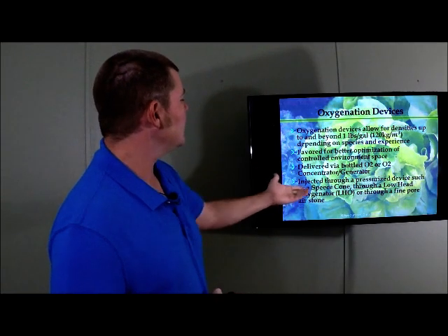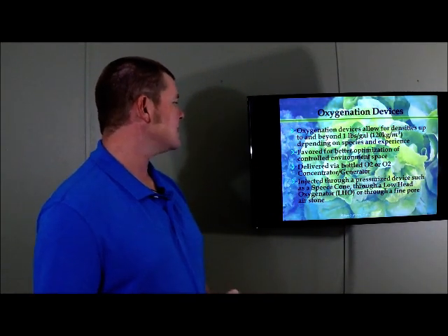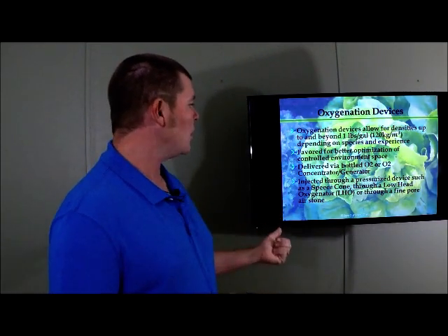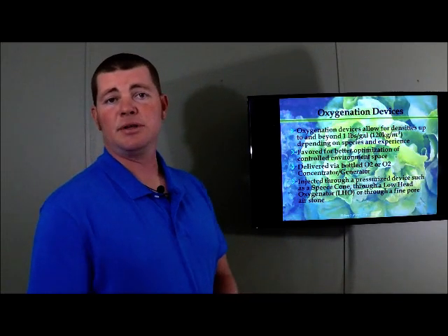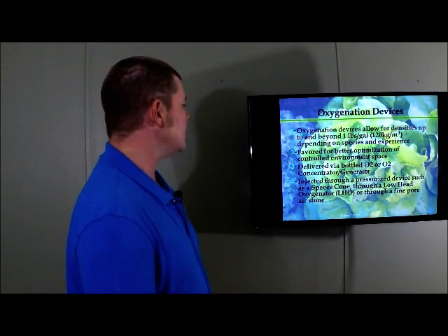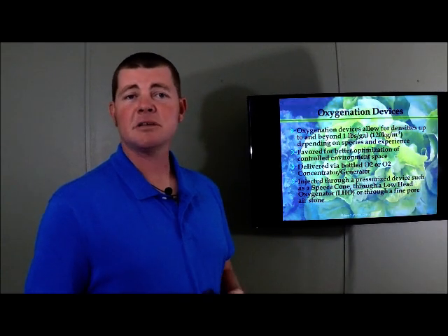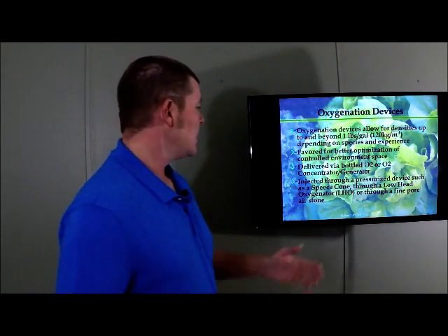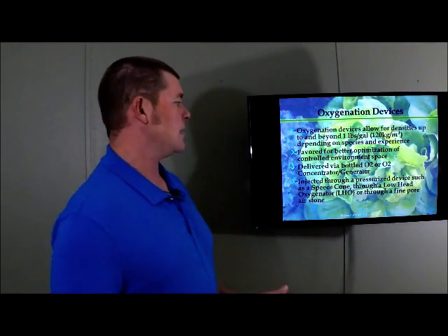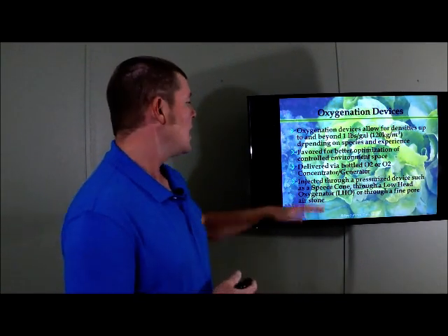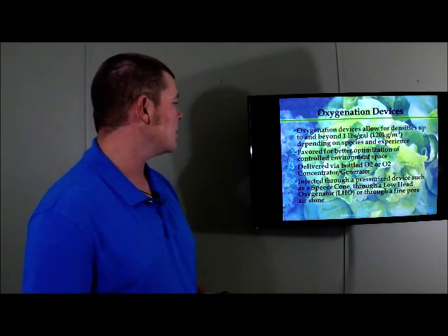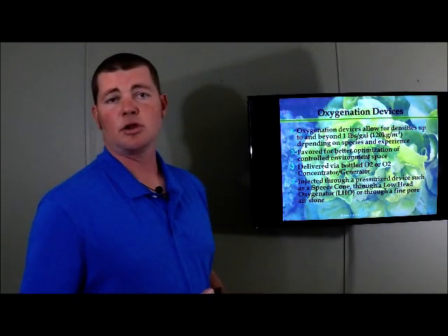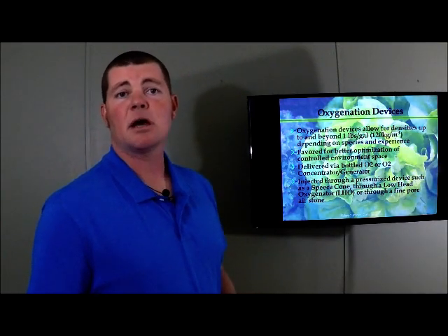So anyways, moving on, we inject that through a pressurized device such as a Spiess cone, which we'll talk about later, a low head oxygenator, or through a fine pore air stone, which is probably the least efficient method. But we want to inject this and try to get as much of that oxygen to dissolve into the water before the bubbles reach the surface. So in a fine pore air stone, again, bubbles will slowly rise and reach the surface. Through a Spiess cone or low head oxygenator, we'll actually completely dissolve that oxygen. Well, through the Spiess cone; a low head oxygenator is a little less efficient, but we'll talk about these when we talk about equipment.